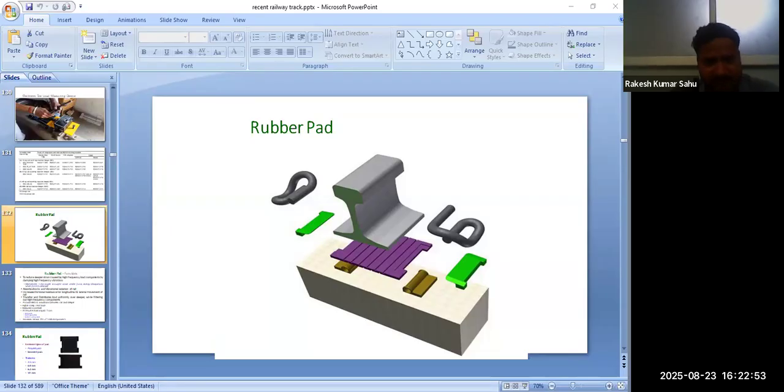Liner are fittings used in conjunction with rubber pad and rail on both sides of rail to achieve correct alignment and gauge, to provide for correct deflection of ERC, so that the ERC is designed to load. That's why liner is a very crucial part of rail fitting. These liner are of two materials, glass filled liner and metal liner. GFL liner, glass filled liner, is used in track circuit area, that is station and yard, and metal liner in block section, in normal section.